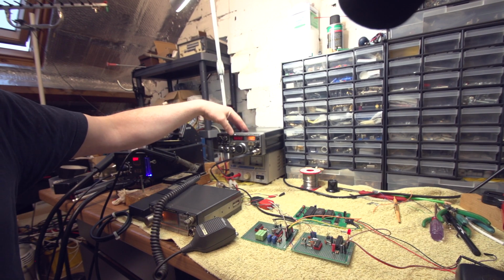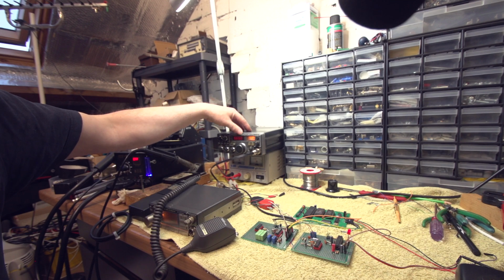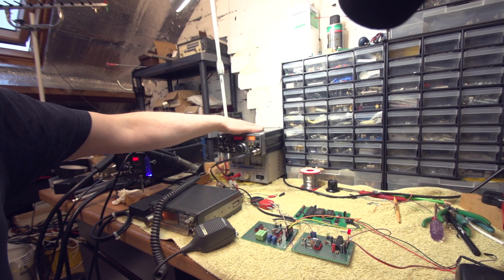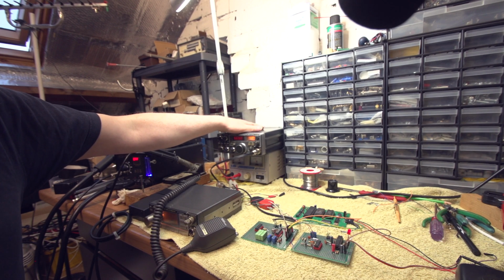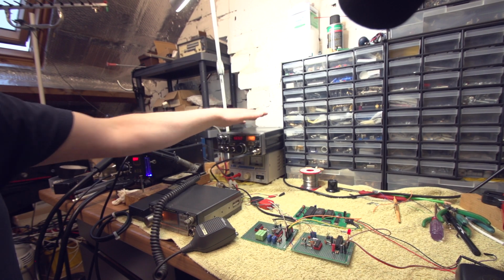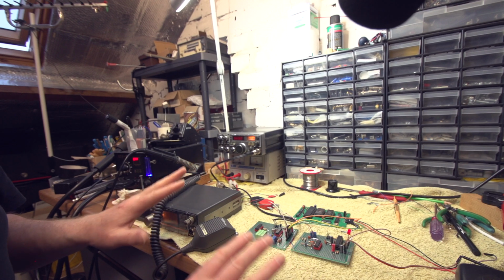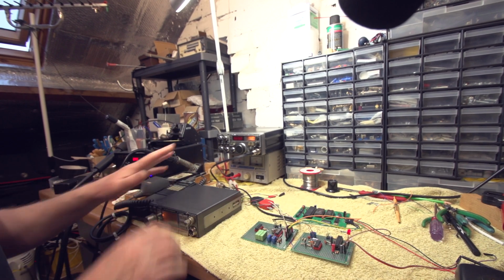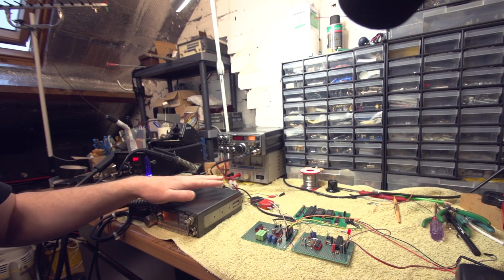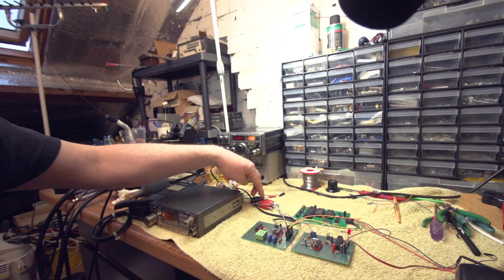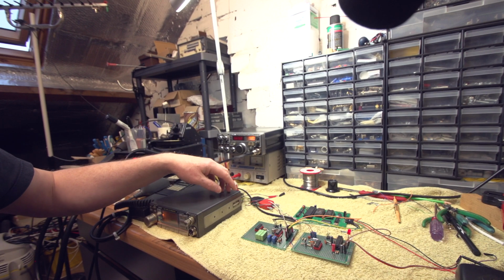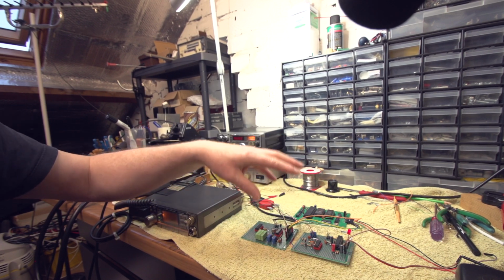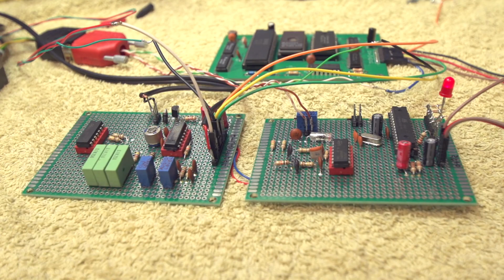So this is tuned to 145.650, same as the IFR. That's transmitting. At the moment it's very low power, about 1 watt into a dummy load. So there's no aerials connected at the moment. This is purely all dummy load, local testing in the shack here. The receiver, which I showed earlier, is connected through these D connectors, and that goes to the logic board, like the controller, and also to the analog board as well.